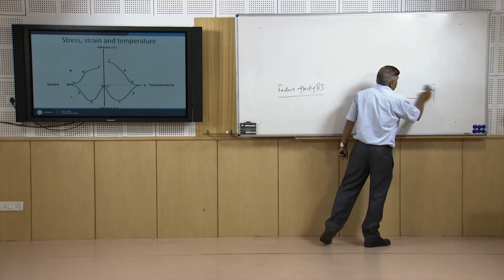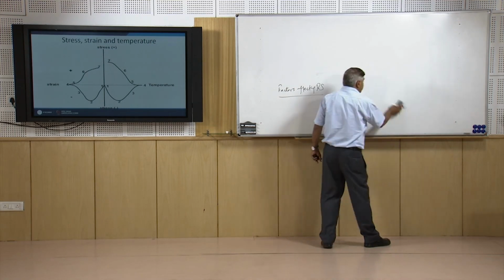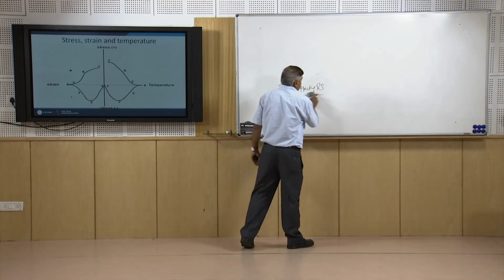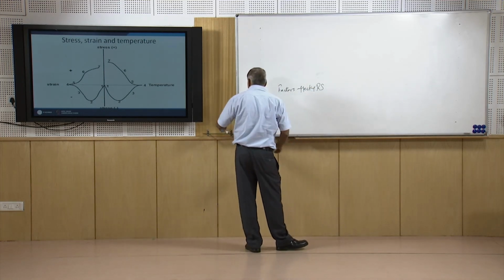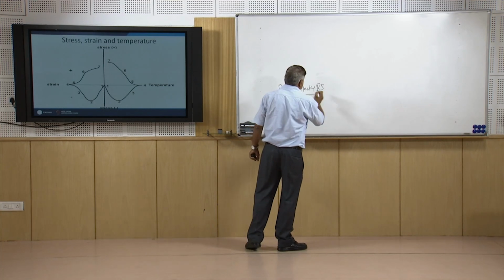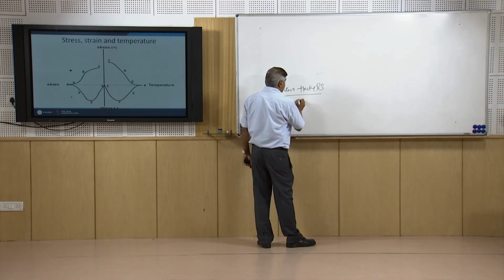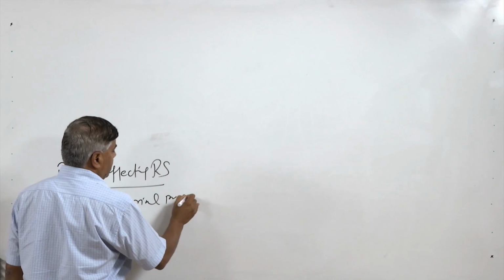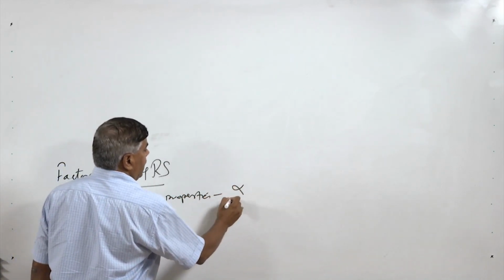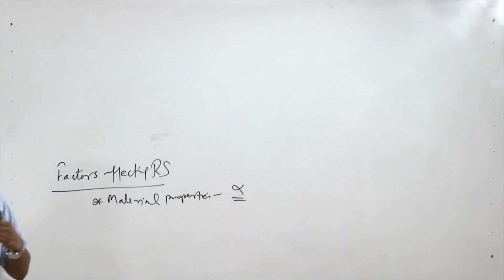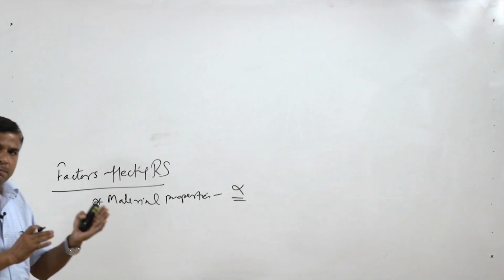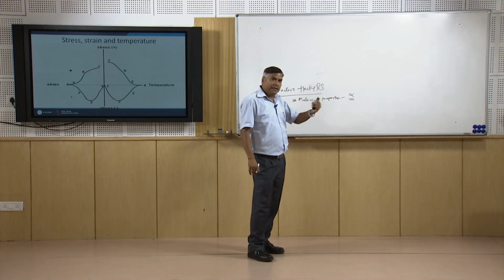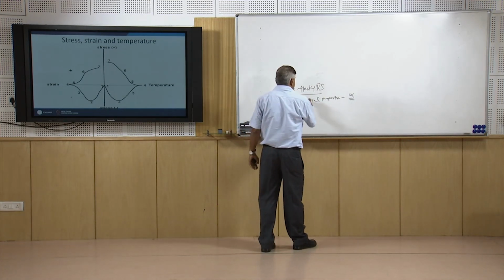So, considering this point, sometimes filler metal is intentionally selected in such a way that the yield strength or elastic limit of the metal is low, so that the residual stress magnitude can be reduced. Now, we will see the different factors that affect the residual stresses. One is the material properties, especially alpha, the thermal expansion coefficient. If the expansion coefficient of the filler metal or the base metal is high, then there will be more expansion and contraction, which will lead to higher locked in strain, and that in turn will cause a higher residual stress value.